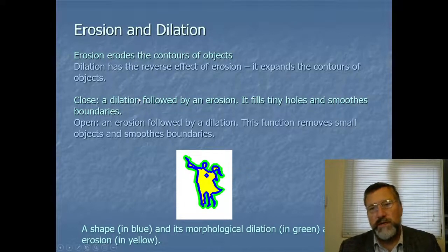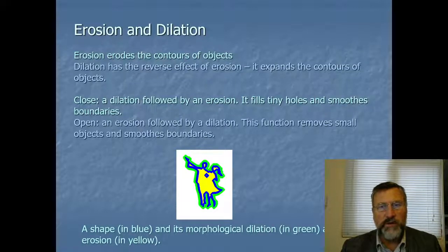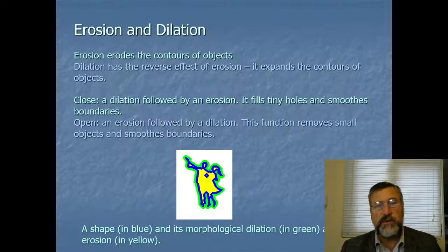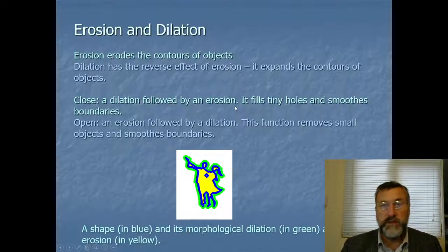Okay, so in LabVIEW, I think you might have been trying to use fill holes, which is a VI that comes with it, which fills in holes in objects, in particles. But you could do it manually by applying these close operations with the dilation and erosion, because that's basically what fill holes is doing.